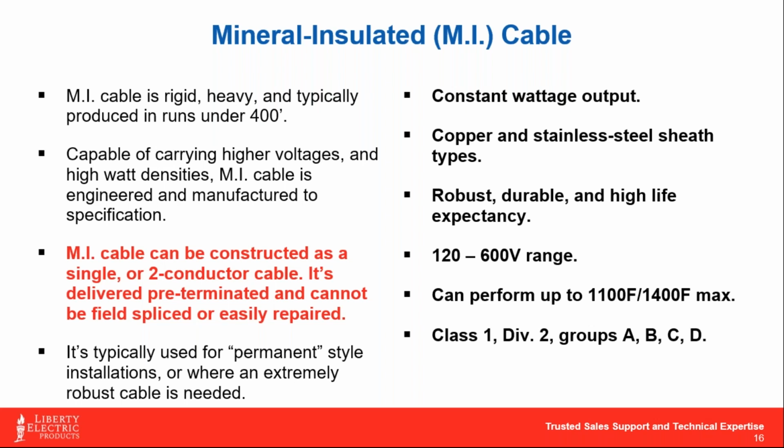The nice thing about these MI cables, they are very robustly built as a metal jacketed product. These things also have to be hydrostatically dunk tested before they can even leave as part of their UL listing. So it's really the most engineered of the heat cables, we could say.